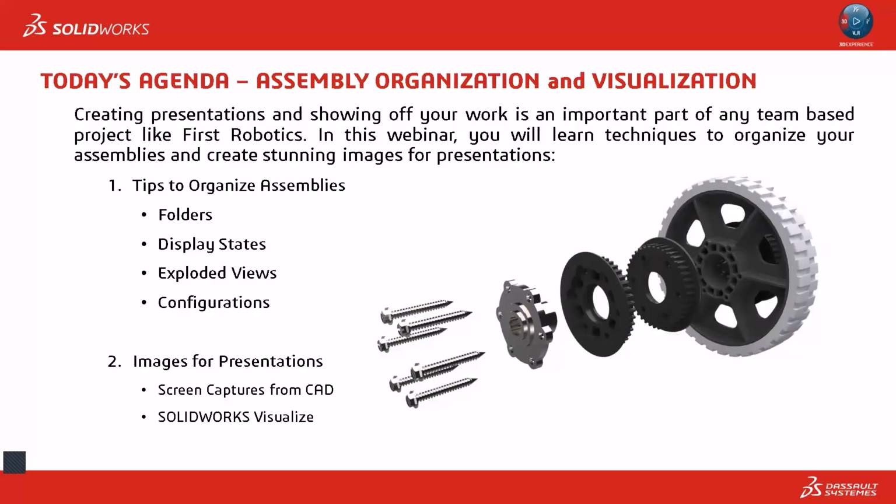Today I've got two main categories that I'm going to talk about. The first one is tips to organize assemblies. We're going to talk about folders, display states, how I use exploded views, and configurations. The whole point of this is to prepare the model for creating presentations and things like that.